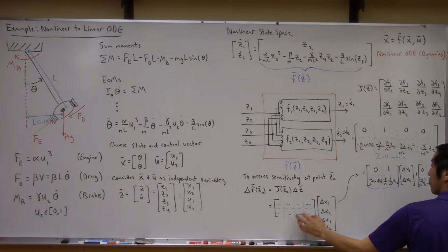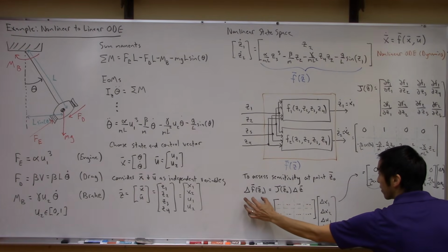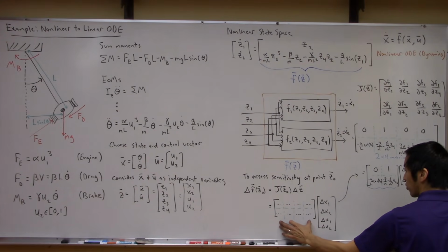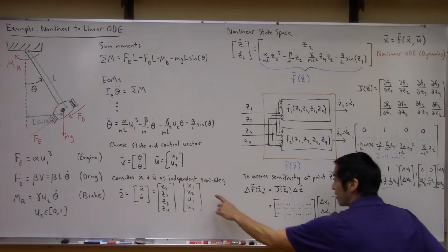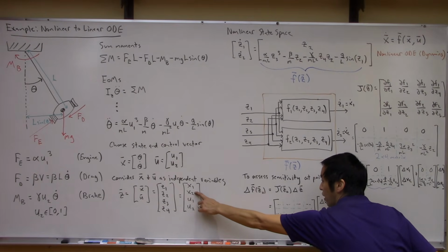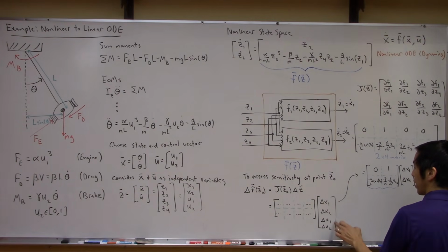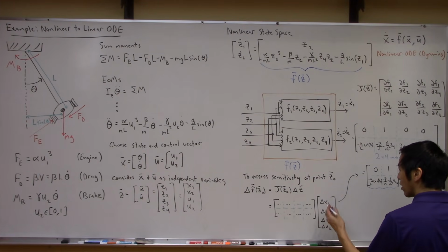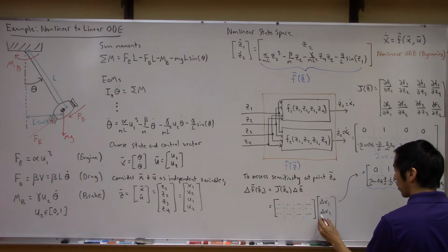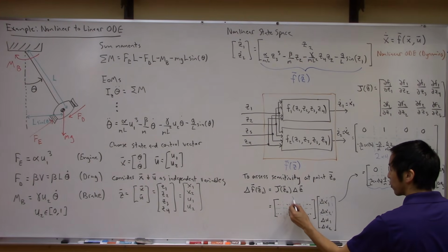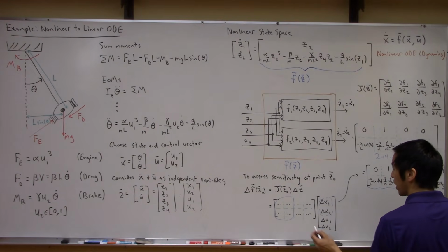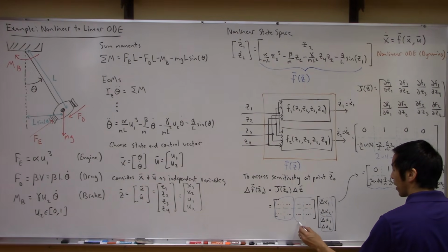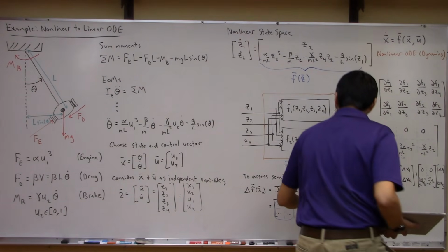So now I can plug it into this equation down here, which is telling us the change in outputs is the Jacobian times the change in input. So it's just this 2 by 4 matrix times delta z. And remember, delta z is just delta of all these: x1, x2, u1, u2. So that's what I'm writing right here. And if you stare at this long enough, you can see that the x terms multiply this first 2 by 2 block. The u terms, or your control vectors, multiply this second 2 by 2 block. So why don't I go ahead and rewrite this.